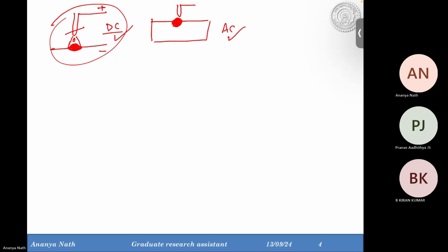So there will be no interruption from oxide layer formation, and in the repetitive cycle you will not get an oxide layer on each deposited aluminium track. So like that, in some materials you need AC. You can go with AC, but DC can also work with electropositive mode.